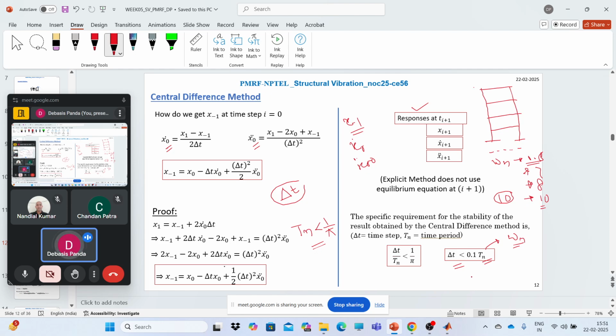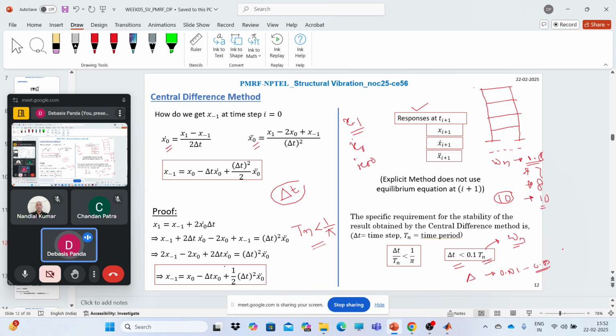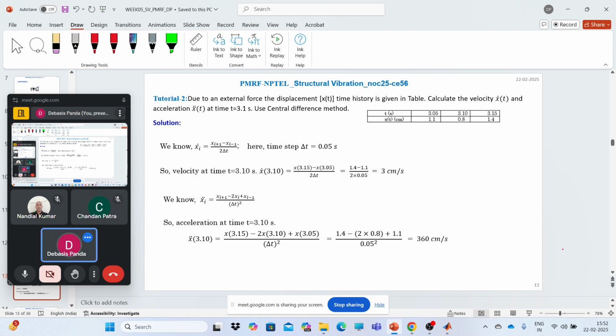Typically the time step del t should be in the range of 0.1 to 0.02 or 0.03 to get stable, numerically stable solutions using this particular method. Now to use the central difference method we have a simple command in MATLAB, LSIM, linear simulation technique. Using that LSIM method we can easily solve for this.